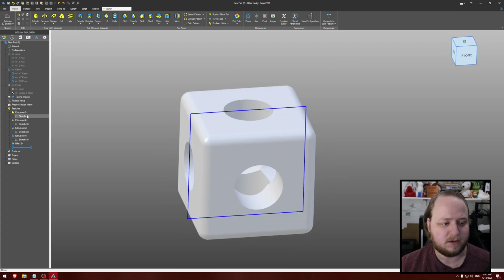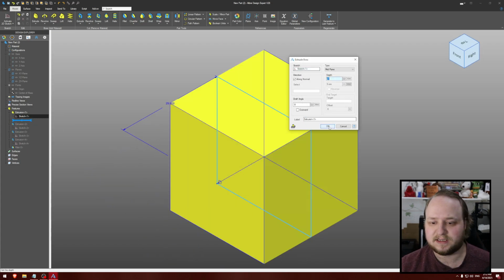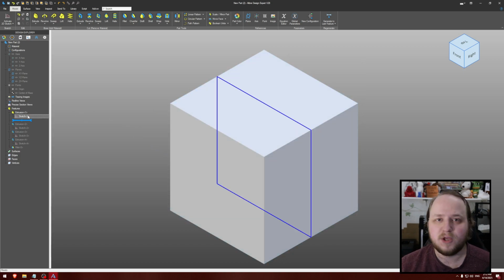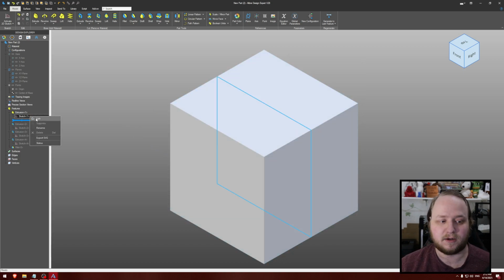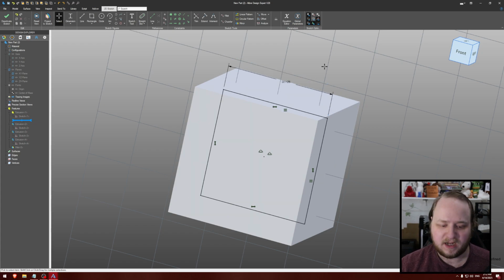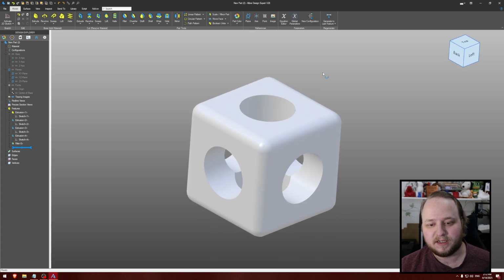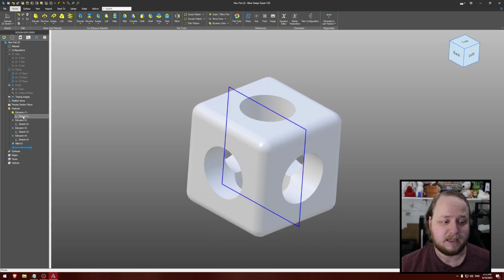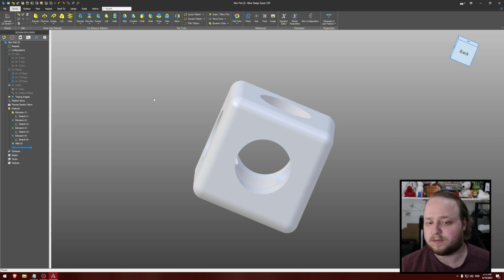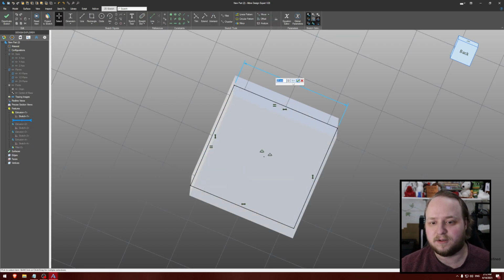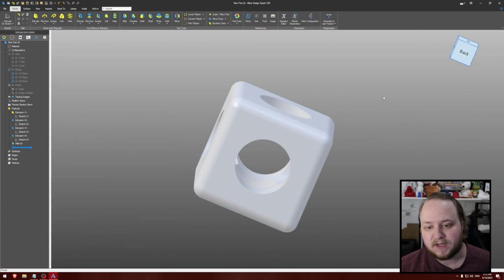Everything changed, including this extrusion, which stays the D1 value. You might have to manually type in the same value depending on your CAD software. Let's go back to 25mm, and let's reload the part, and we're back to exactly what we started with. That's how powerful CAD can be. Because if you manufacture this, whether you 3D print it or otherwise, and you decide it doesn't quite fit how you wanted it to, maybe the part is slightly too big and you forgot that plastic expands a little bit, you can do, say, 24.8 and reload the whole part.